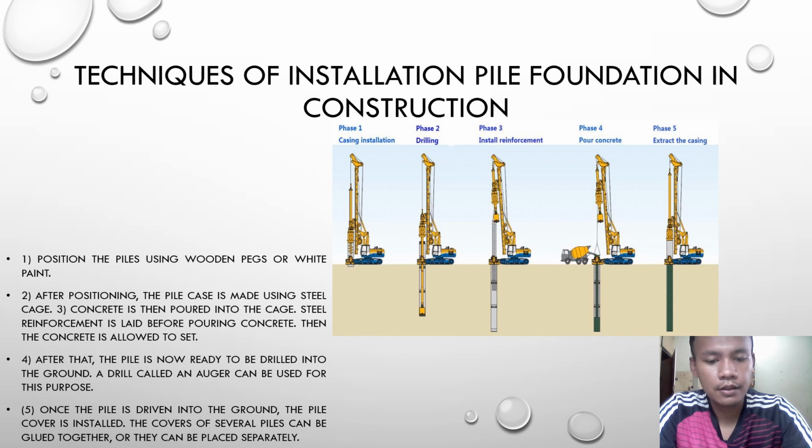The driven pile method is an ideal option because it least disturbs the supporting soil around the piles and results in the highest bearing capacity for each pile. Since every pile has a zone of influence on the soil around it, piles must be spaced far enough apart from each other so that the loads are distributed evenly.